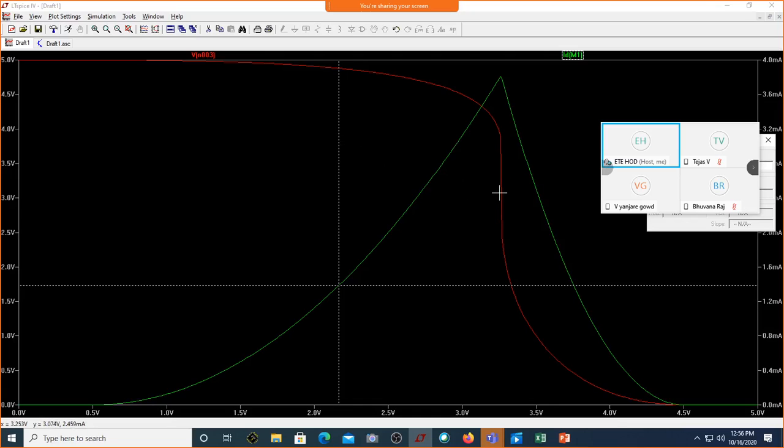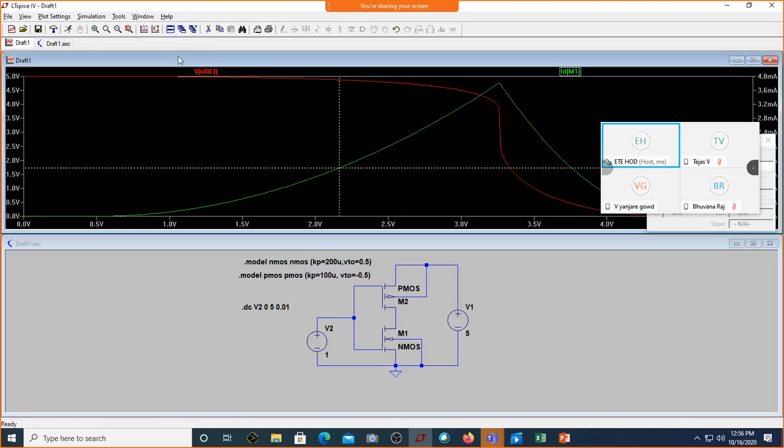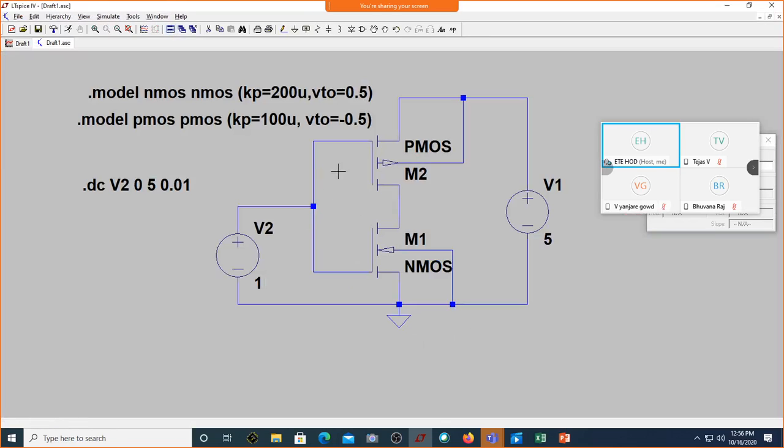I can shift it to any point depending on the dimension of the MOSFET, because there is no other variable available. Do you have anything other than the dimension for this transistor? Nothing. Of course, the input voltage comes from the external side, and this is the supply voltage. Supply voltage you cannot tweak, and the input voltage is an independent parameter you have no control over.